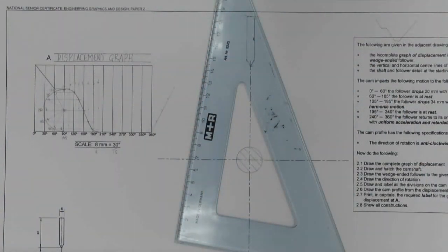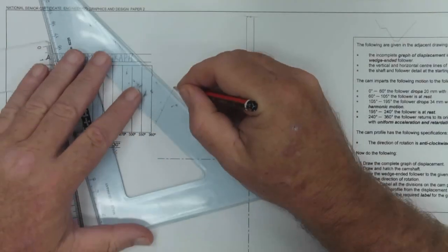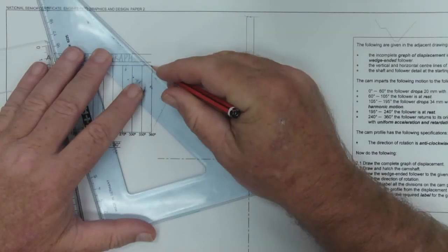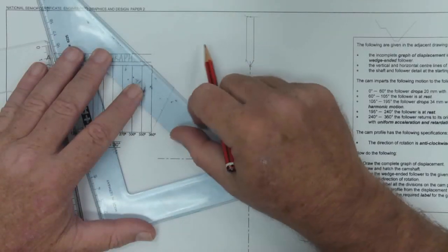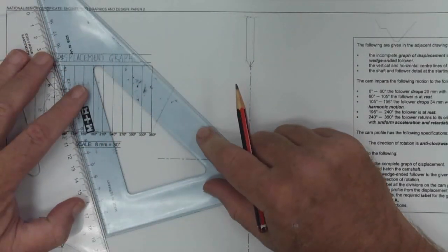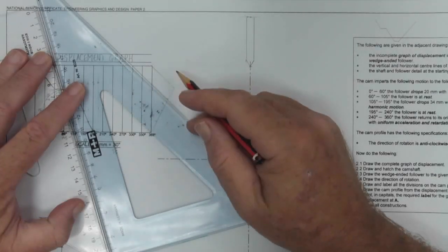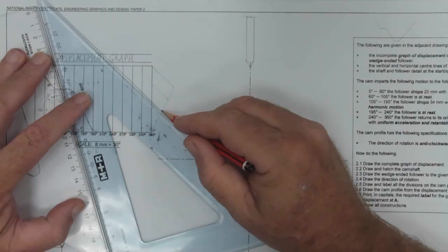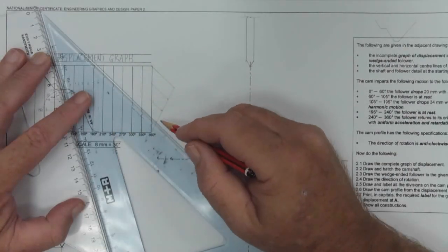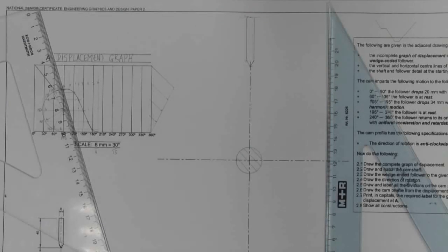And now what we do is we line up the last line to the end point at the top of the shape, get that angle, line up our set squares together, then we'll slide this one down so that we can draw a parallel line and there are those 4 points.